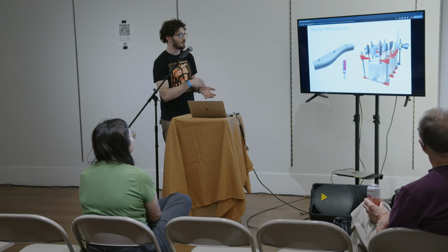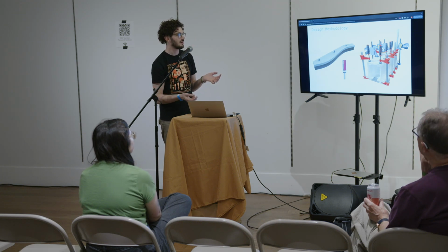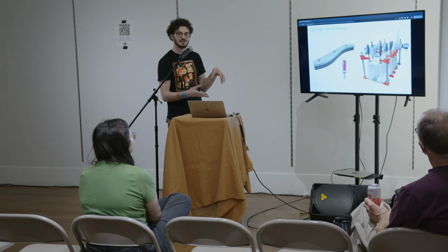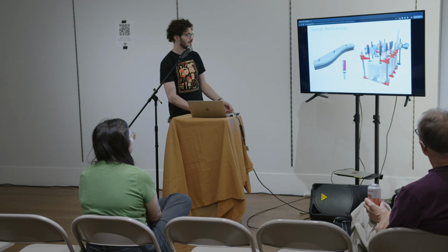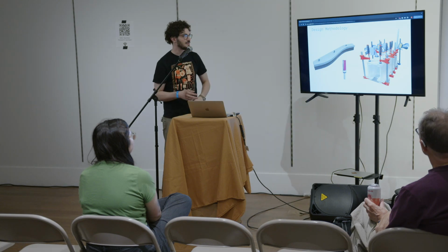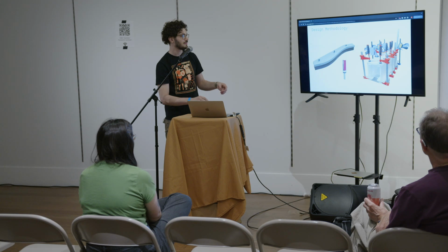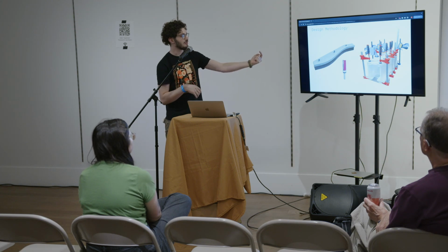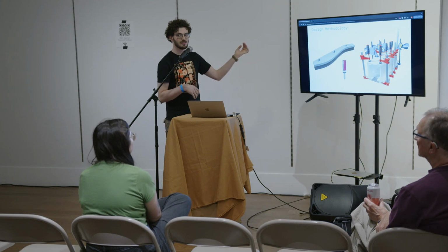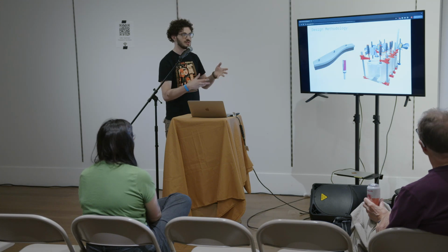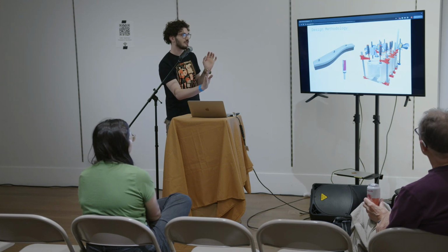In order to get some of the more complicated geometries we needed, we ended up using a pattern routing bit. So if you haven't seen this, it's a ball bearing that's the same diameter as the cutter, and you stick this in a table router, and then we just bandsawed to a line and sanded a piece of MDF that has the profile that we want, and then by running the bearing along the MDF, it transfers that shape to the acrylic. So we can get these precise, repeatable, very nice 90-degree angled cuts in acrylic, again, without using any digital fabrication tools.